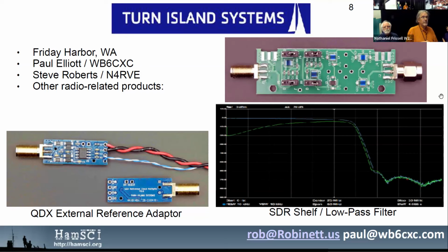It is important to understand that good recordings require that the whole system be accurate and free of excessive RFI, and the only easy way to do that is to look at the whole spectrum and make sure that your antenna system and grounding system are working well, and that RF distribution doesn't introduce imperfections and interference into your measurement set.